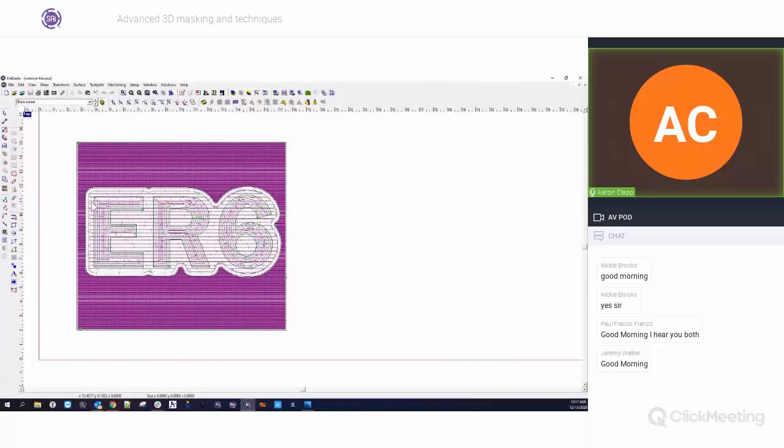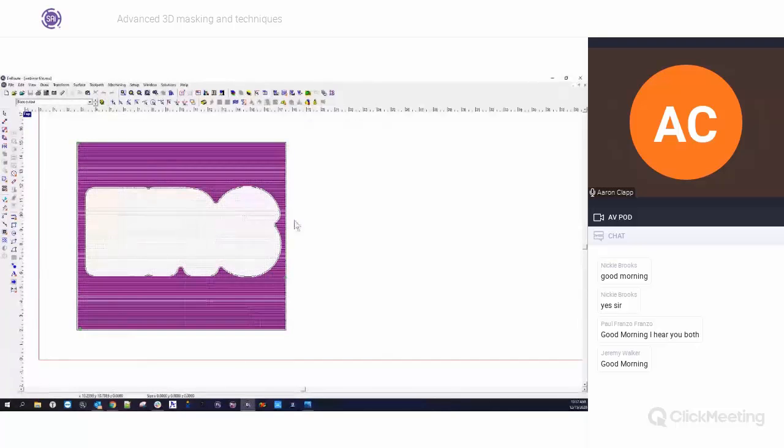And what I did was I created an outline by using this tool here. I did an offset close contour, and then I applied an offset to it. I can't remember, I think it was maybe 0.25 or so inches, maybe 0.5, away from the edge. And it created this nice little boundary. So what this is going to do is create a unique base for my letters.